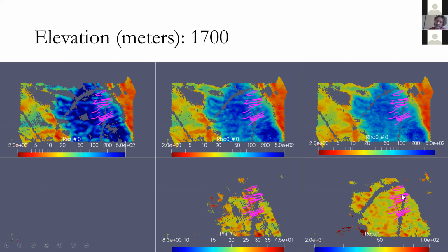These are the elongation of the IP anomalies that were found on the ground, and there is really a nice correspondence between the place where we have IP anomalies on the ground and the place where we have IP anomalies in the inversion of the airborne data. And again, the direction of these anomalies is really matched well, comparing the ground-based data and airborne EM data.